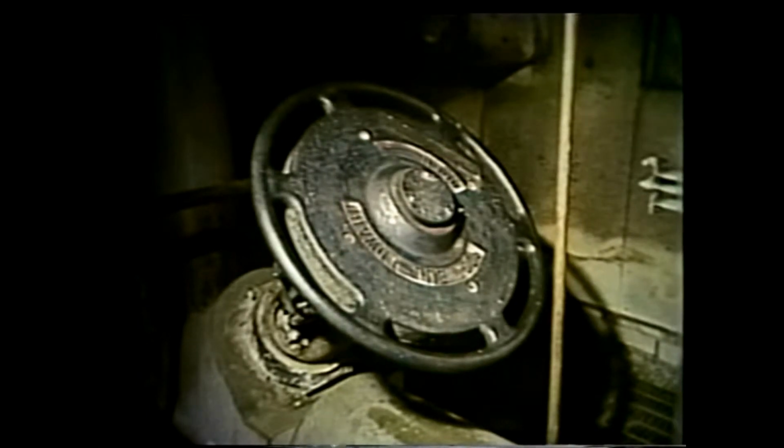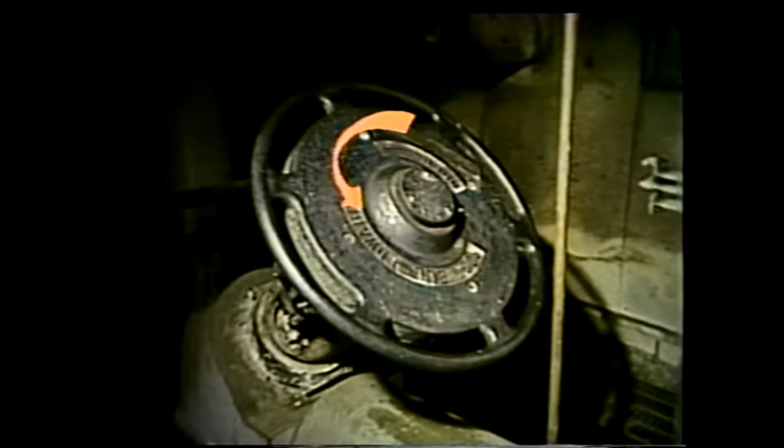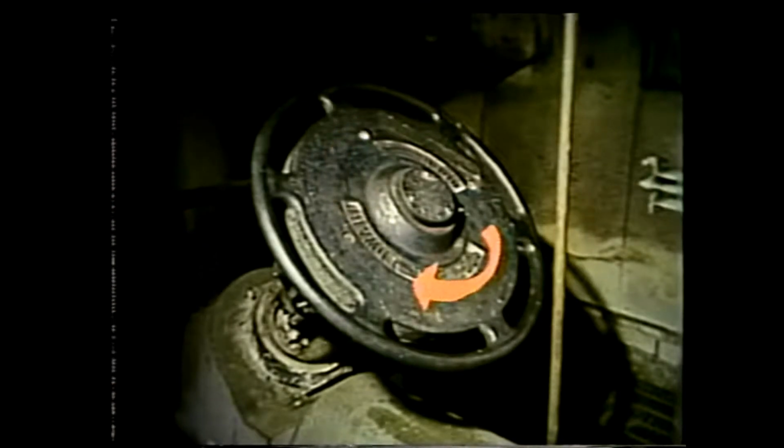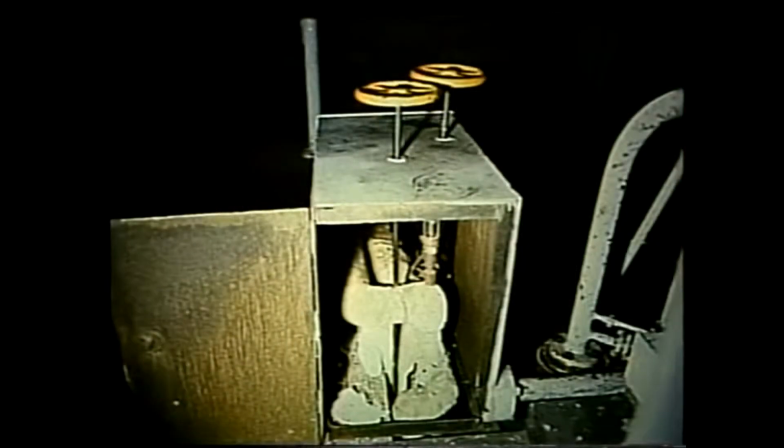The valve is opened or closed in this way. First, the hand wheel is turned in the opposite direction of the desired rotation. Then it is turned as hard as possible in the desired direction, slamming the stem into motion to raise or lower the disc. Hand wheels can be equipped with other types of adapters to make them easier to operate. Sometimes a chain running through a pulley is attached, or an extension arm might be put on the hand wheel of a valve that's hard to reach.